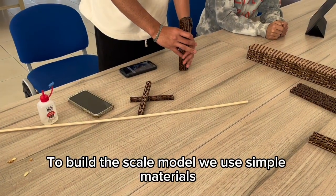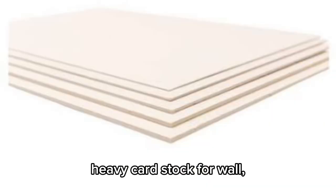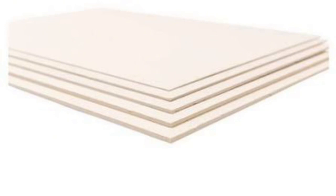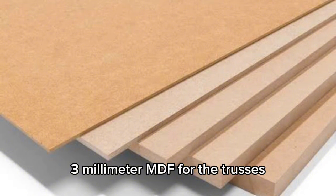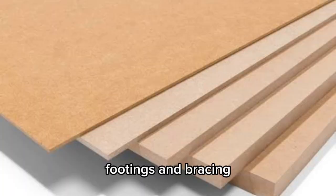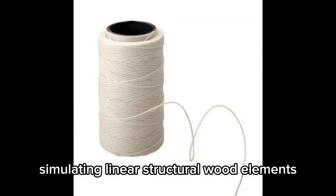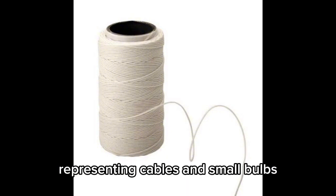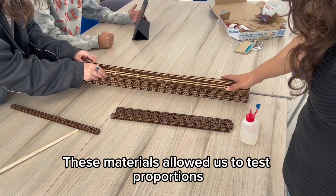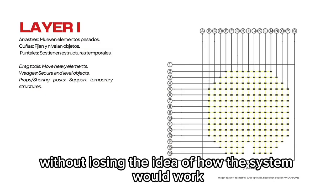To build the scale model, we used simple materials, but each one represents a real system. Heavy cardstock for walls, ceiling, and furniture, simulating light panels such as drywall and plywood. 3mm MDF for the trusses, representing steel trusses or structural frames, footings, and bracing. Balsa wood for the purlins and supports, simulating linear structural wood elements. Thread for the installations, representing cables, and small bulbs to indicate the pavilion light fixtures. These materials allowed us to test proportions, modulation, and joints without losing the idea of how the system would work in a full scale.